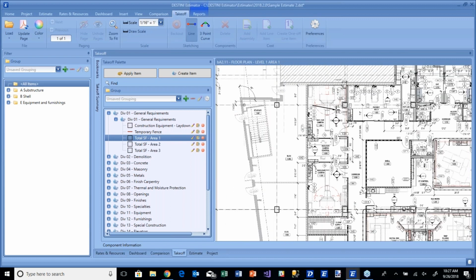While I'm sketching, one of the things that we provided as well is if you hold the Shift key, it will maintain that vector, so it'll keep sketching on that line, which will make it a lot easier when you know you've got that line to come through and then pick your endpoint.